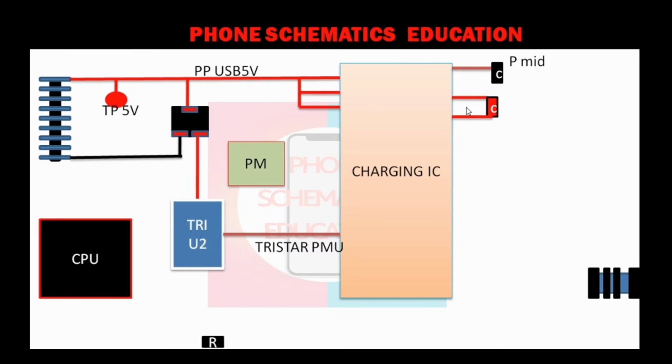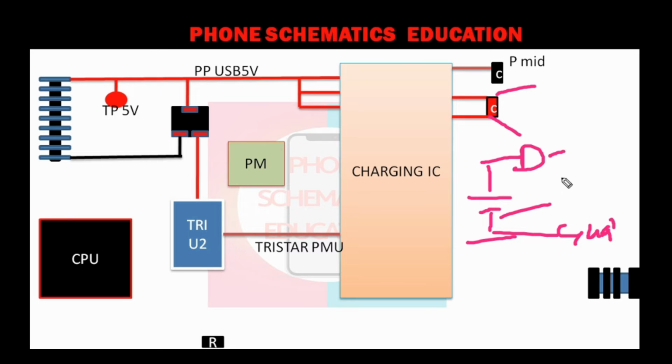Right? A capacitor connected in series. This capacitor is connected on both sides to the IC. Now when you check this capacitor with the multimeter on diode mode, you will see a different diode value on both sides. With most capacitors, you get a diode value on one side. Right? On the other side, this capacitor is most of the time connected to the ground pin. These capacitors are connected on a parallel line.